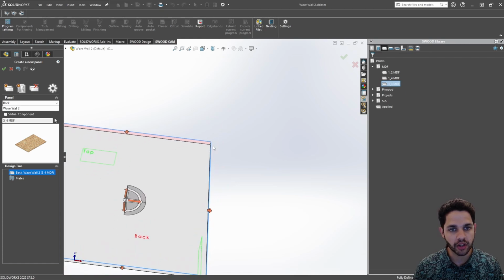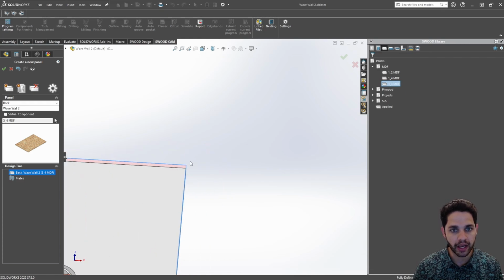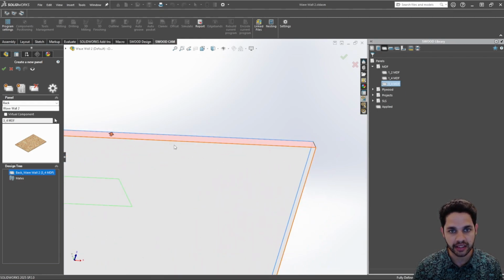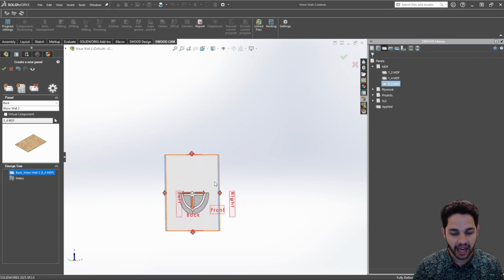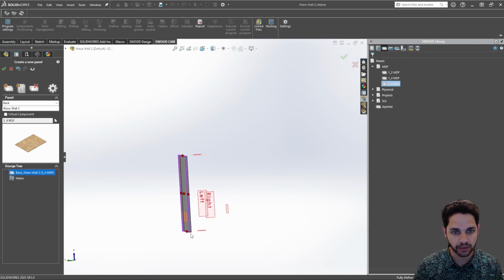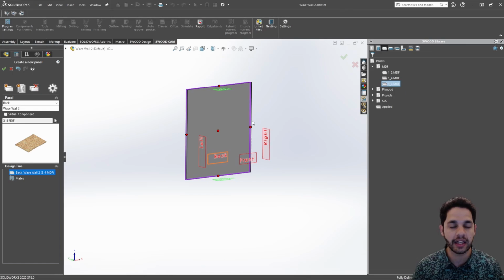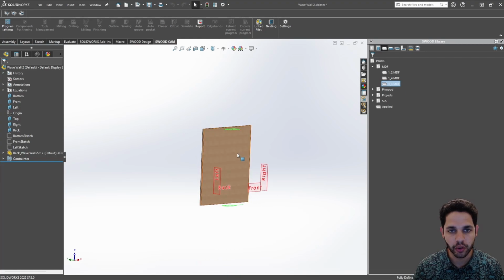So we're going to press R to rotate that because my panel is going to be longer this way as opposed to this way. I want from this edge to this edge to be my length. And as you can see, that's there. So I'll make that my length, and I can hit C as a shortcut to constrain all those panels in place and do a quick visual check to make sure those are all aligned, which they are. So I'm going to hit the checkpoint, and that panel's in there. So cool.